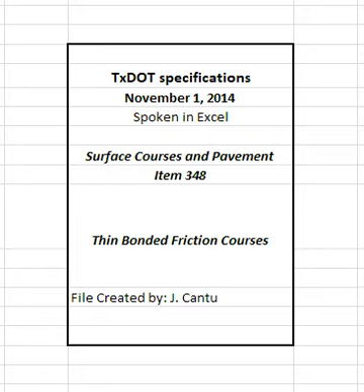4.4.2.2.9 Approval of JMF3 and subsequent JMF changes. JMF3 and subsequent JMF changes are approved if they meet the mixture requirements shown in Table 8, the master grading and binder content limits shown in Table 7, and are within the operational tolerances of JMF2 shown in Table 9. 4.4.2.2.10 Binder content adjustments. For JMF2 and above, the engineer may require the contractor to adjust the target binder content by no more than 0.3% from the current JMF.